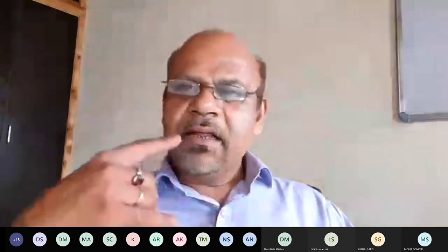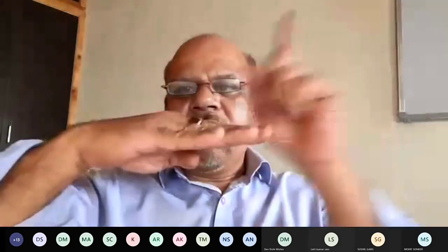We have already seen that the induced C is caused by the vertical soft iron placed forward and aft. The two conditions we have seen: the compass is here, and there may be a rod forward, above or below, or aft, above or below. In these cases, the rods will become either positive or negative and affect the compass, creating a deviation. I think we have seen it on the diagram.